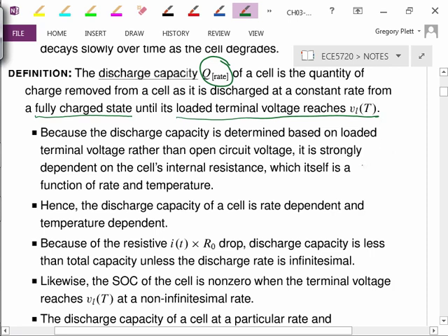The terminal voltage, V equals OCV plus hysteresis minus diffusion minus IR. Let's at least pick on IR, if nothing else. If current is big and R is non-zero, then V is going to encounter V_L far before OCV encounters its limit because of this IR term here.